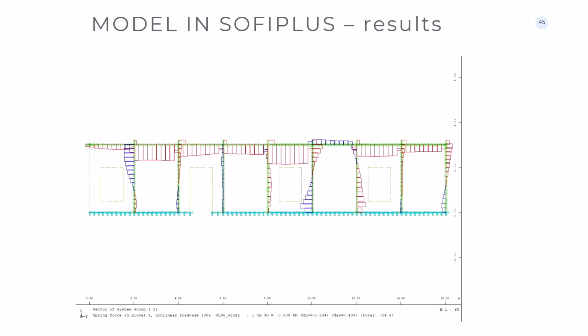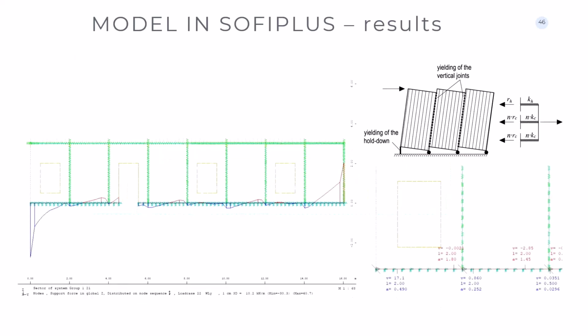So when the wind is blowing this way, you would expect that if you apply a load, then this force is constant, or it doesn't invert, but it inverts because this panel rotates with respect to the other, because this connection here is not rigid. So when you apply the wind here, it's not receiving a compression, it's trying to rotate like this. And then you get compression forces, tension forces, and you get the same behavior on the edge. And this is extremely important to establish how many screws you have to connect the two elements. And you see here the behavior.